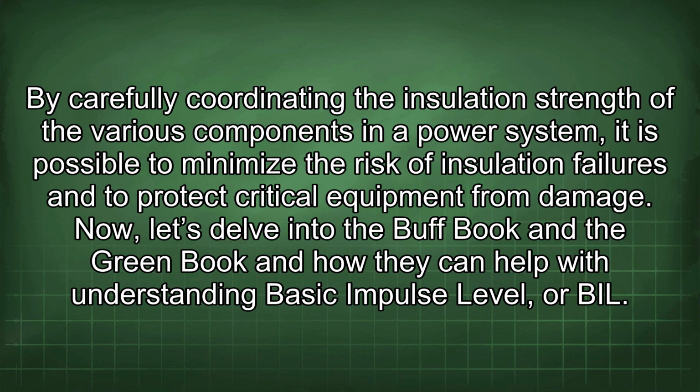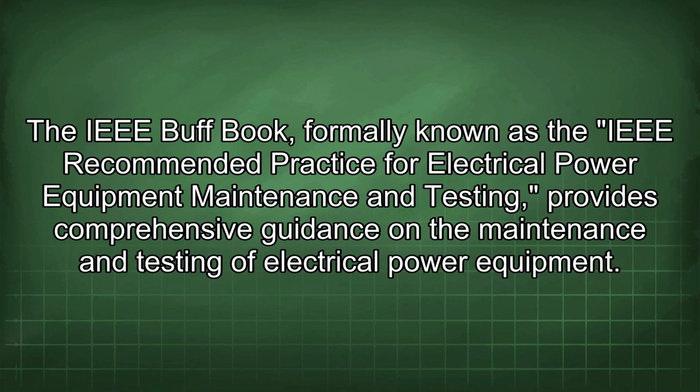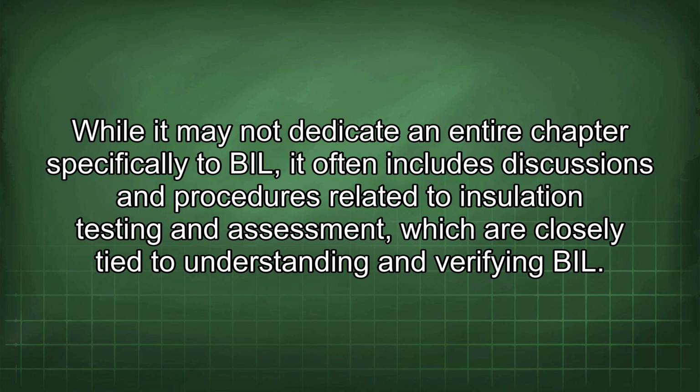Now let's delve into the BOF book and the Green Book and how they can help with understanding basic impulse level, or BIL. The IEEE BOF book, formerly known as the IEEE Recommended Practice for Electrical Power Equipment Maintenance and Testing, provides comprehensive guidance on the maintenance and testing of electrical power equipment. While it may not dedicate an entire chapter specifically to BIL, it often includes discussions and procedures related to insulation testing and assessment, which are closely tied to understanding and verifying BIL.